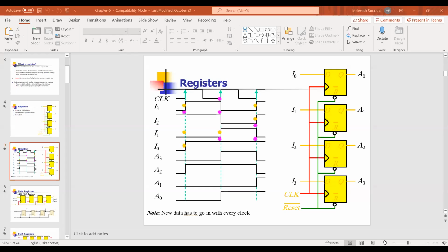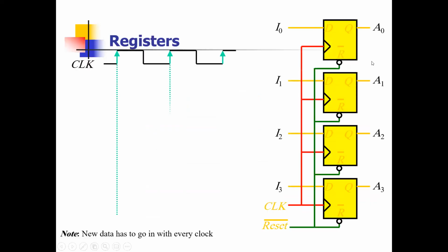Here, this is a shift register, girls, and you can see we have 4 flip-flops, which means it is a 4-bit register, and these are D flip-flops. As I taught you in chapter 5, about the direct input, you can see here we have R, the direct input, and we are using a reset button, and all are connected together to the same point.